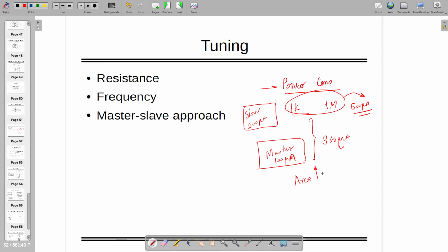But GM is in feedback, so make sure that you are designing everything with the inductor. Everything has to be designed with the inductor, and then you need to remove it. This is just for simulation. With the inductor, whatever results you are getting need to be quoted, not the ones without the inductor, because what you are seeing are comparator results, right? It's an op-amp as a comparator, right? I think this clears your doubt also.